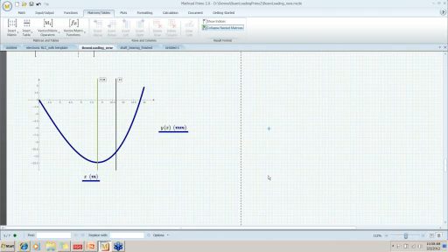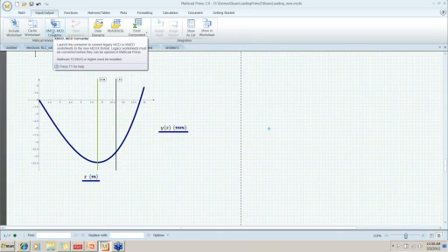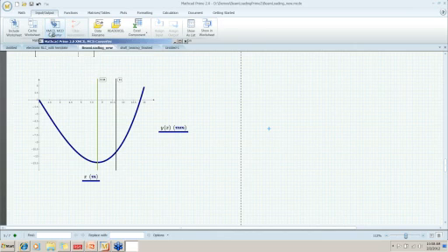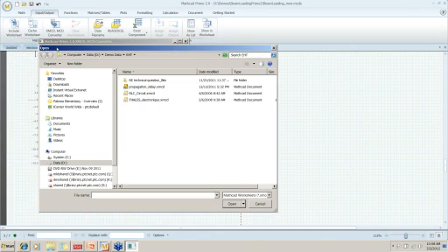So when you open Prime 2.0, you're going to go to the Input-Output tab, and I'm going there now. I just clicked on the Input-Output tab, and on this tab, right here, there's a button called XMCD MCD Converter. That will take your old files and convert them. When you click on that button, you're going to get this little converter utility, and you're going to click on Add Worksheets.